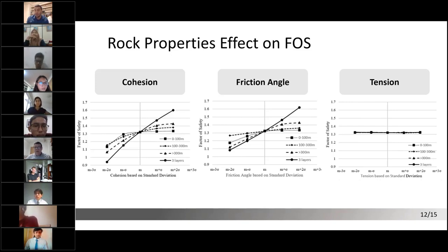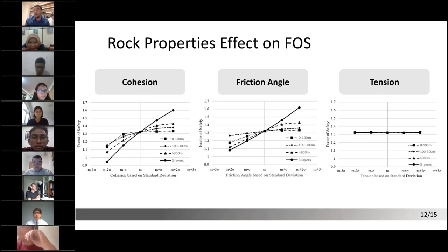We did the sensitivity analysis changing one parameter at a time, according to the possibility of these parameters occurring in real life, and then we calculated the factor of stability according to that value. So the sensitivity analysis has been done on one increment of one value at a time.